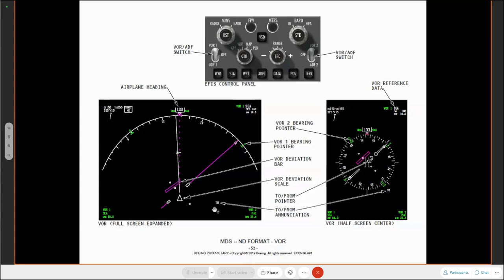Okay. Down here we've got two VORs on the aircraft, VOR number 1 and number 2. Down here we've got both of them tuned. Again, they're normally tuned automatically by the flight management computer. It will use VORs to triangulate the position for the flight plan, and the system will automatically tune to the best VORs to give a position fix. So on here we've got VOR 1, VOR 2, Seattle, okay, and Payne Field, and they both have co-located DME transmitters. So again, we can see the range there in slant range in nautical miles. Okay.